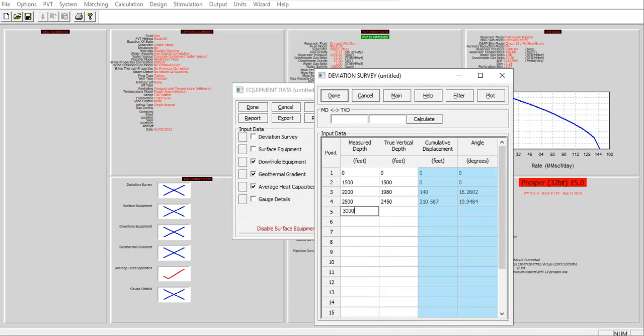Actually it's a deviated well, but in the IPR section, we input the deviation as 0. That's okay, because basically what we did in that section, we wanted to calculate the skin due to deviation. Let's neglect that, it will not be very big. So we input 0 just to make the skin factor quite conservative.